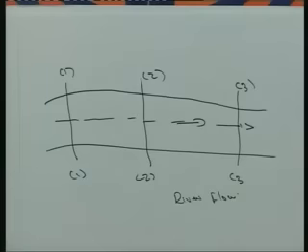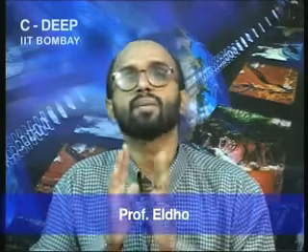So, all the fluid flow which we are dealing with is 3 dimensional in nature, but depending upon the problem, to simplify it we can consider the fluid flow as 2 dimensional or sometimes as 1 dimensional. These simplifications make the problem analysis much simpler and the interpretation of results much easier without losing much accuracy. So, in most of the problems, even though they are 3 dimensional in nature, we may be solving them as 2 dimensional or 1 dimensional fluid flow problems.